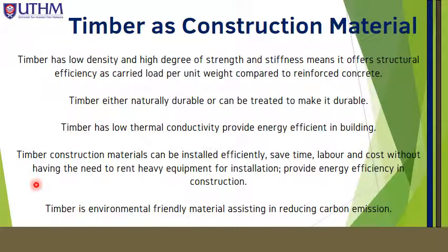Why do we choose timber as a construction material? Timber has low density and a high degree of strength and stiffness, meaning it offers structural efficiency as carried load per unit weight compared to reinforced concrete. Timber is either naturally durable or it can be treated to make it durable. Timber has low thermal conductivity, providing energy efficiency in buildings.